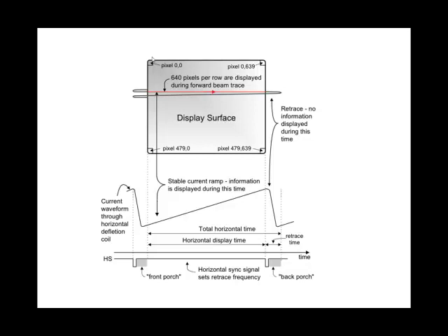Now you may be asking yourself, why do I need to understand how the CRT works? We're using a flat panel LCD in the class. You're right, we are not using a CRT, but as said earlier, the timing signals used on a modern LCD follow the same signaling requirements of the old CRTs for backward compatibility. The LCD contains a digital circuit that will interpret your VGA signals and recreate your display based on your signal timing. For you to create such an image on the screen, you must create the horizontal sync and vertical sync timing signals, as well as the color signal.